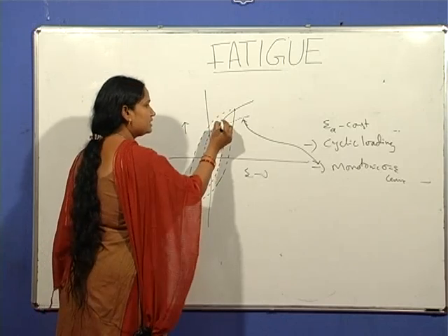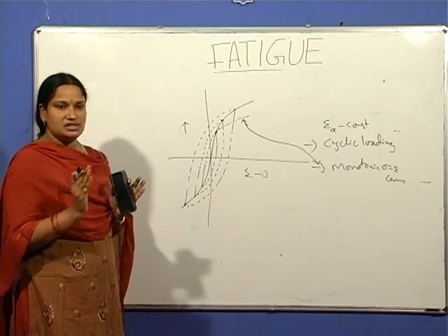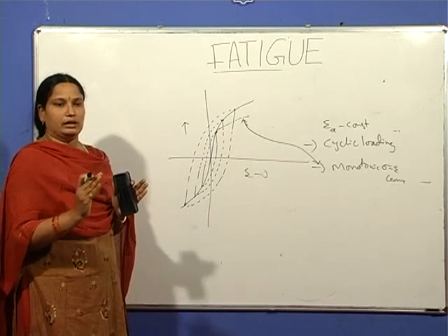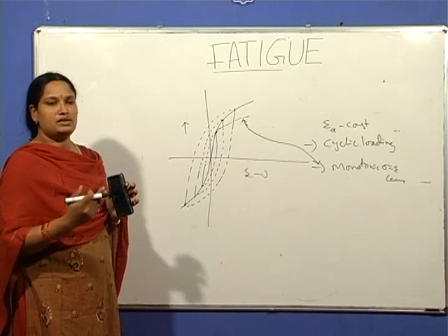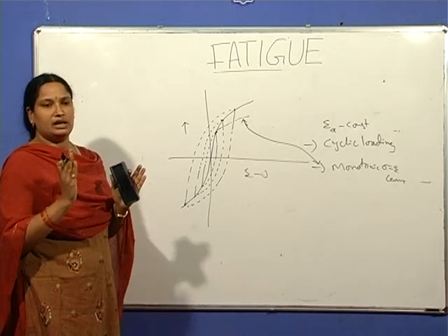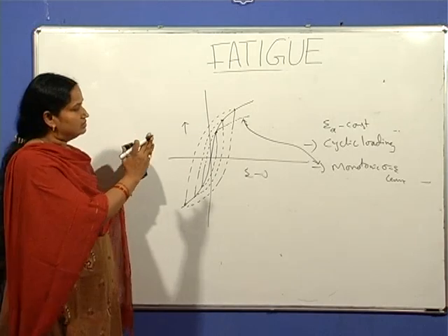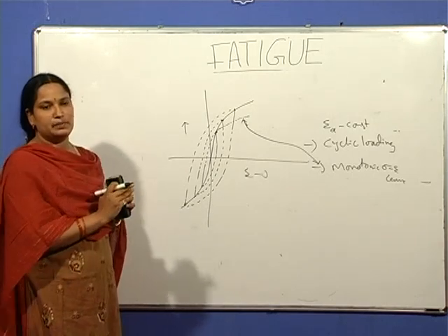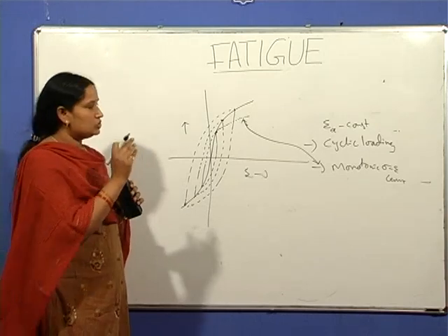Similarly, for the second experiment, where the constant strain amplitude is different, the material is subjected to cyclic loading, and again after a few hundred cycles the material undergoes saturation, where the cyclic stress strain behavior, that is the hysteresis loop, stabilizes.